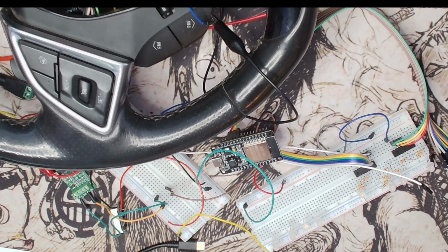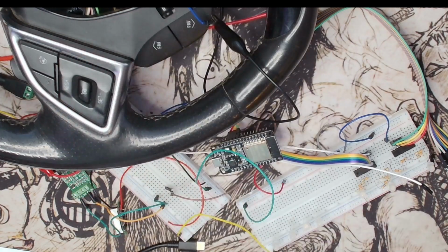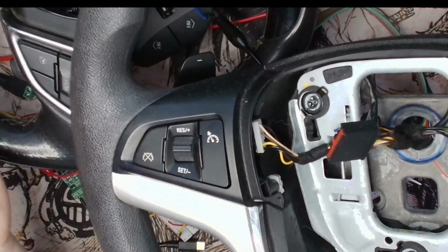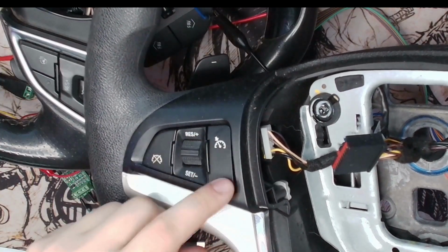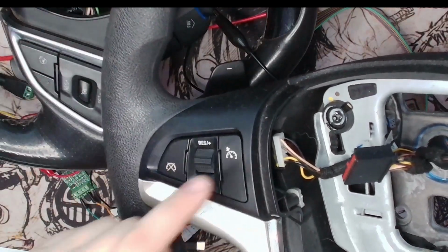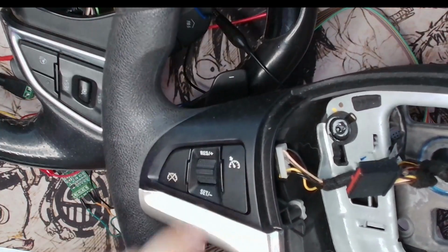So, remember, if we go back to how the cruise control was designed and what potential issues we may face, you'll remember that on the original steering wheel, there was a toggle switch which allowed you to turn your cruise control on and off, right? So we have this, that you press it and now cruise control stays on, and that allows us to have continuity in our resistance ladder, and as soon as we press that, it breaks it. Now, the other thing to think about is none of these buttons should function whatsoever unless this button is engaged.